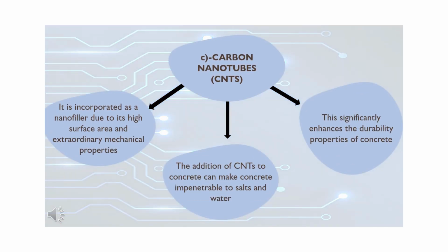The third one is carbon nanotubes. They are incorporated as a nanofiller because of their high surface area and extraordinary mechanical properties. Their addition makes the concrete impenetrable to salts and water, which enhances the durability of the concrete.